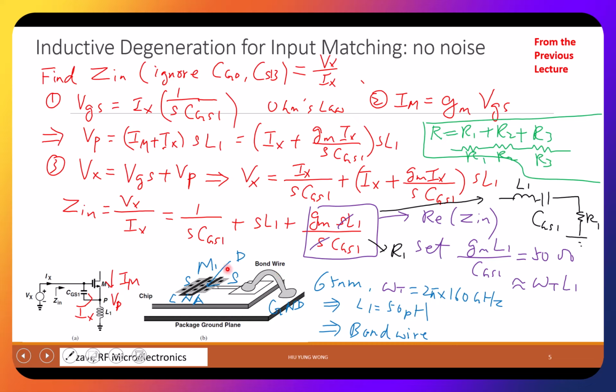And here again, if you can understand this drawing, then you know what you're doing as a circuit designer. Here is just the transistor M1. You have the source, and the middle is the drain. We call this a multi-finger structure. We talked about this earlier. In order to reduce the gate resistance, instead of having a very wide transistor, this has two times the width you are seeing here, because this is just like two transistors, right? The current goes from drain to the left, and then from drain to the right, and the source is connected. So you just have two transistors in parallel. This is a finger layout, multi-finger layout. Forget about the name, interdigitated layout, okay? And this is the source. Any questions? Not about the math, but about the concept. Is that okay?